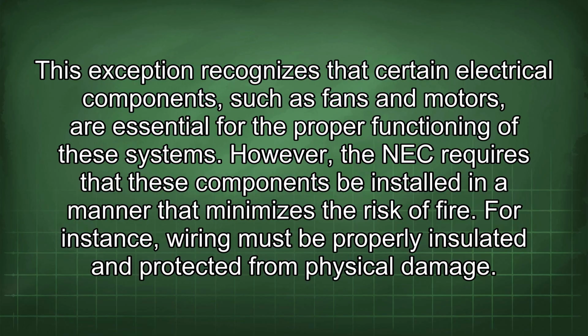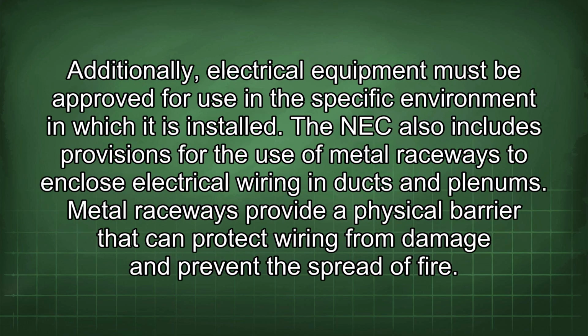For instance, wiring must be properly insulated and protected from physical damage. Additionally, electrical equipment must be approved for use in the specific environment in which it is installed. The NEC also includes provisions for the use of metal raceways to enclose electrical wiring in ducts and plenums. Metal raceways provide a physical barrier that can protect wiring from damage and prevent the spread of fire.